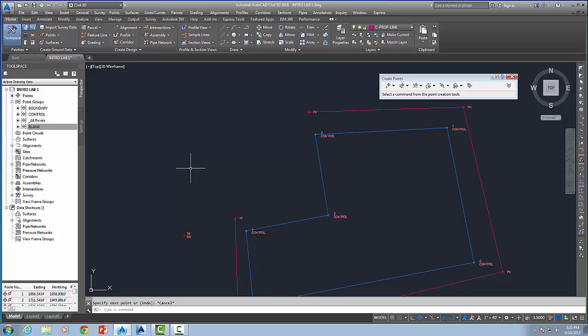So from a resolution standpoint, if you were doing surveying, you would have to know why you're going to do that. We're going to do a bearing-bearing intersection, just because I want to show you how these bearing things work. So we're going to use the bearing from 9. We're going to hold that bearing, the 1 degree 47 minutes 4 seconds, and then we're going to hold the other bearing from 11, 88, 12, 56.